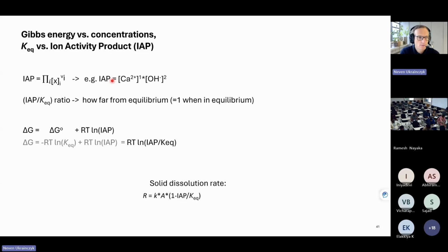That's the saturation. And any further ion you put inside, if you reach saturation, you will start to precipitate portlandite. And that ion can be either OH minus or calcium 2 plus. So any further ion starts to precipitate portlandite.